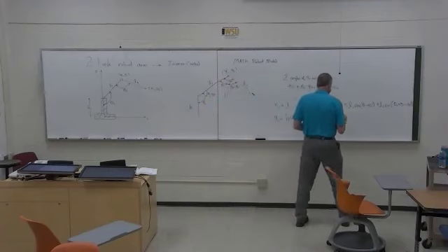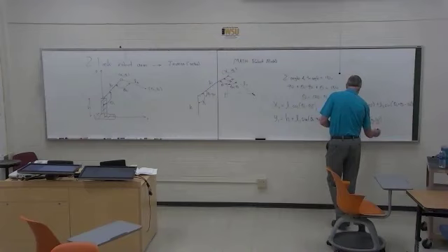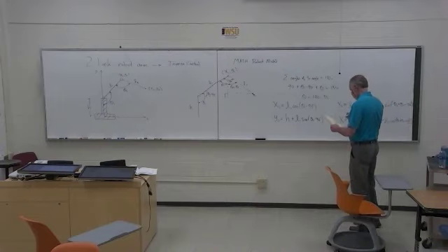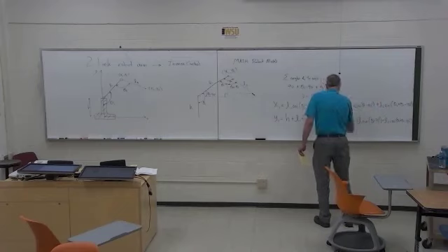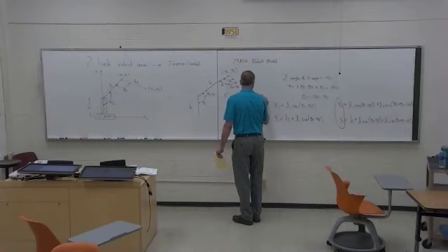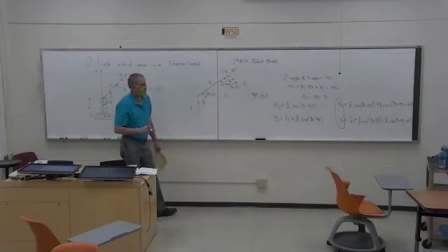And then y2 is going to be y1 minus L2 cosine of that thing. And this is what we really want here. This tells us the position of this end effector as a function of these two angles, theta 1 and theta 2, that we can set on the motors.